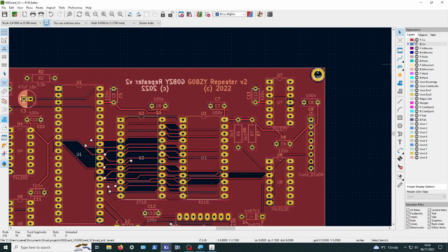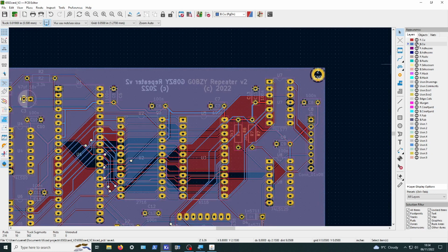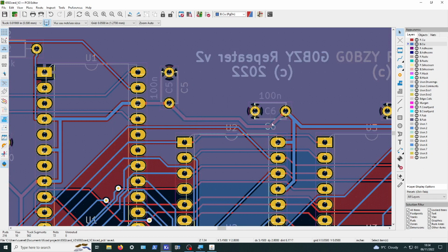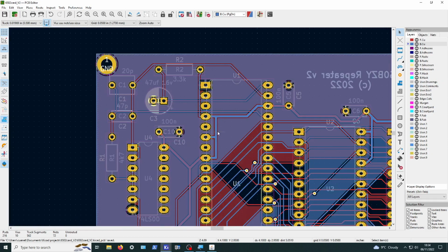When you put on the back copper, you can see that it continues on the back side of the board, again uprated to drive that chip, and then we'll come through this track here, which is uprated all the way through to the processor. It's a better design.